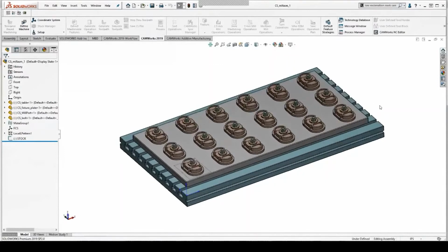This is one of the nice parts about SOLIDWORKS CAM, that you can access the assembly files and actually work within that environment. So if you happen to have some complex fixturing or clamping involved, you can set up void zones, you can set up clearances over those particular clamps just to account for any possible interference. That's something you cannot do on the model side easily. On the single part side, you'd have to actually draw some of the void zones yourself and then set the parameters for it. This one, the models are already setting the parameters for you.